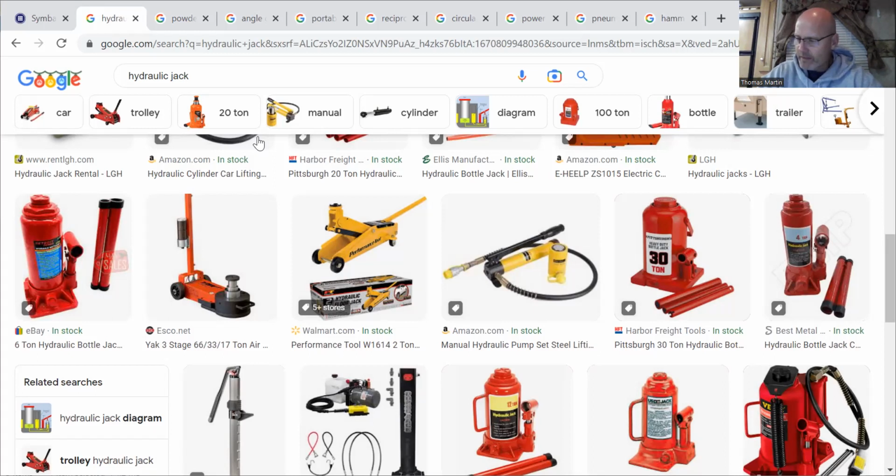We're just going to go over a couple things because title blocks, we've been drawing a few of them in class, and I've been having you draw the long rectangle, but put it into 3 portions. I think I had you put what period it is, what's your name, and then put down at the bottom the date. The date is part of the revision because that's when we know when it was most currently drawn, or if any modifications were done. We always look at the revision date to determine when is what on this drawing here, where does it fall as far as how many modifications has been made to it, either by the customer, engineer, or contractor.